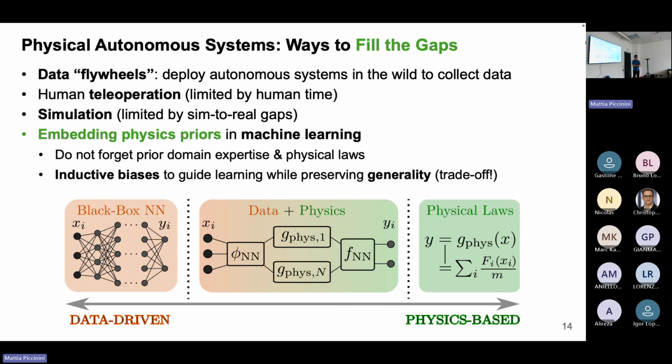Yeah, indeed, when we're talking about purely physical models, if you have a rigid body system, a multi-body system, for example, of your robot, this may have an order of hundreds, at most thousands of parameters. They are very, very complex models. But most of the times, when we are talking about physical models, we are on the order of magnitude of tens or hundreds of parameters. And we need to identify these parameters. This is a challenge, of course.